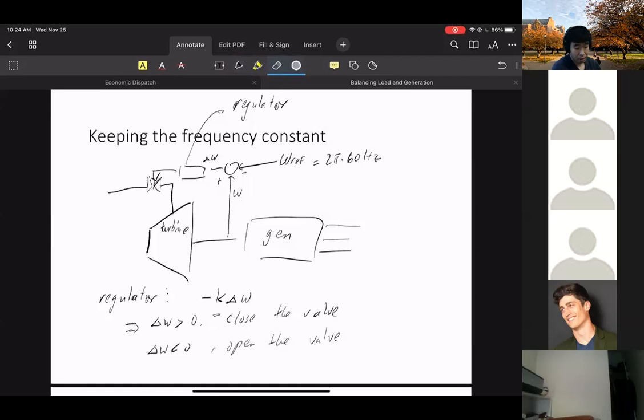I also have a question about the Jacobian matrix in the homework. For the generator, we know the V set is just voltage, so we only need to calculate the angle theta.